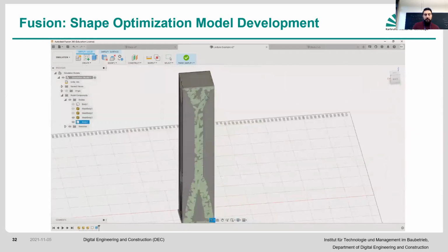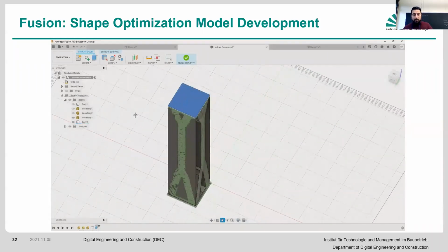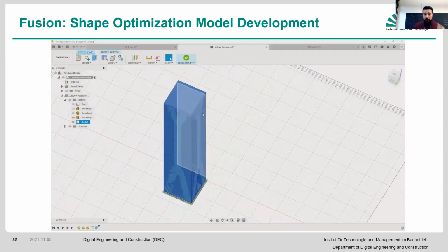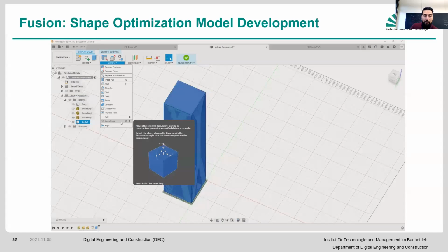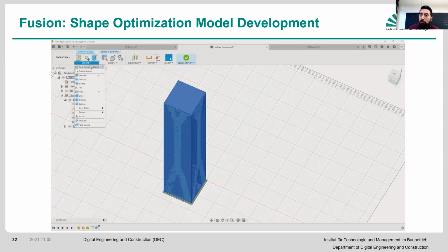Now what you have is a situation where you want to have a completely symmetrical, let's say, surface on the other side as well that needs to be extruded. So what I do is I go to the create again, and I go to the modify, and I try to see how I can actually rotate this. Essentially, my objective is not necessarily to directly rotate it, it is to create what we call a polar array of this.